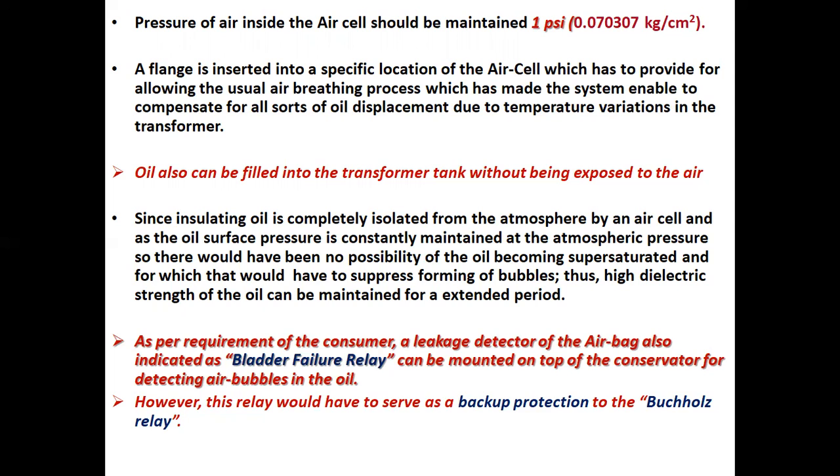Oil also can be filled into the transformer tank without being exposed to the air. Since the insulating oil is completely isolated from the atmosphere by an air cell, and as the oil surface pressure is constantly maintained at the atmospheric pressure, there would be no possibility of the oil becoming supersaturated, and that would suppress forming of bubbles.